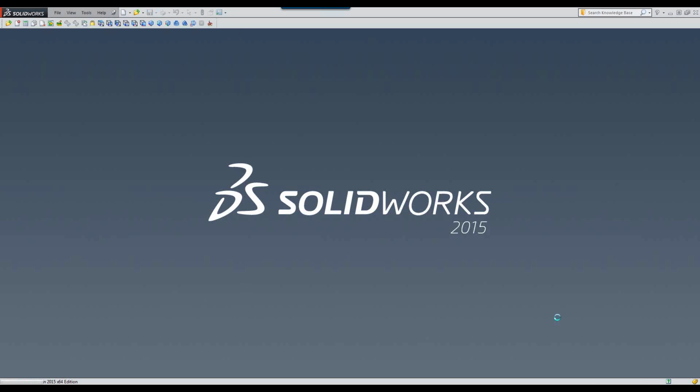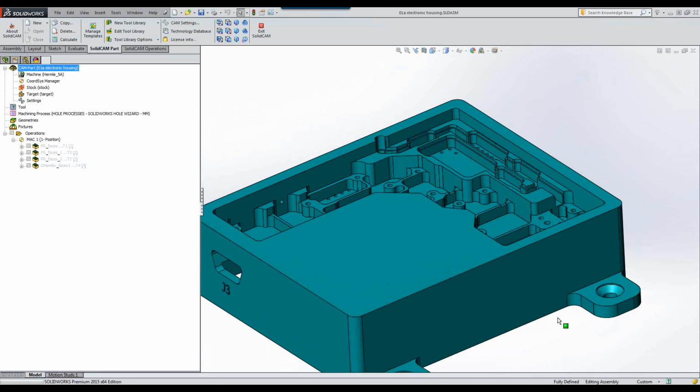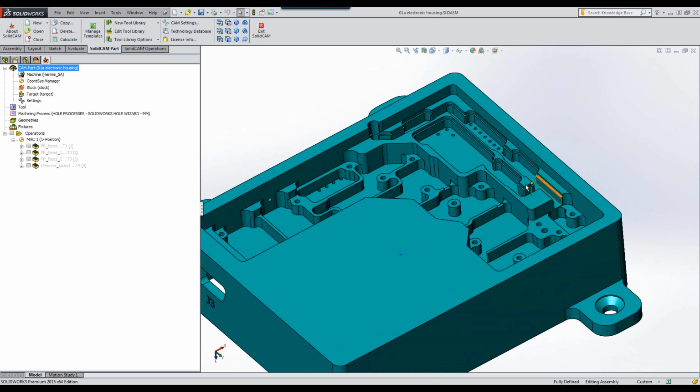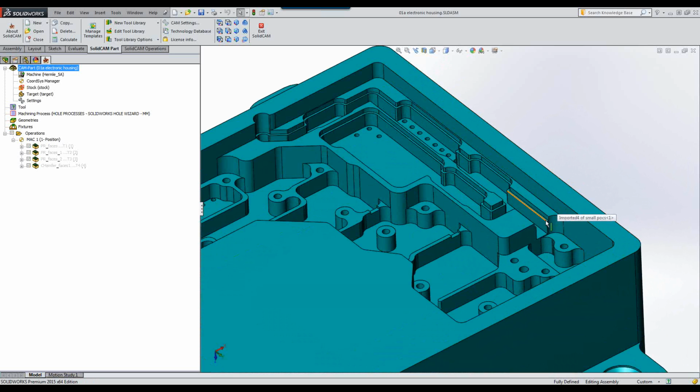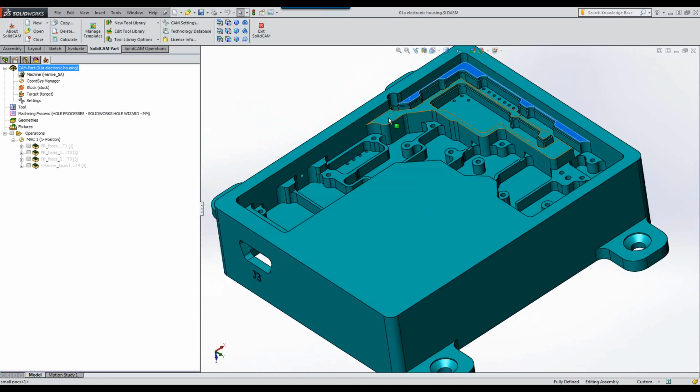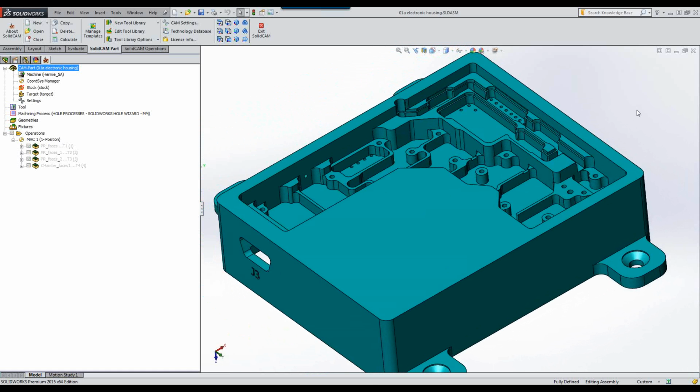Now, this next part is something that's typically seen by people who are doing all different small electronic components. As you can see, there are small pockets over here to different depths. You also have little ledges over here. All of these small areas, these surfaces over here, if you wanted to do this in a regular pocket operation or profile operation, first of all, just the chaining itself would take you a long time. And each operation is individual by itself. So there's a lot of work that can be done over here. However, we can make it a lot easier by using the pocket recognition.